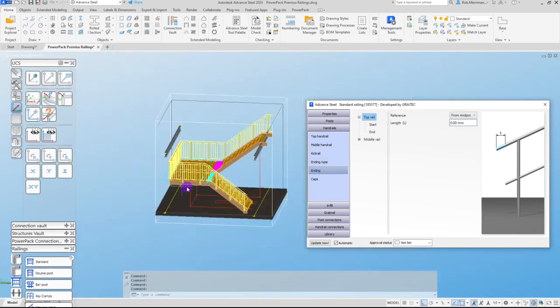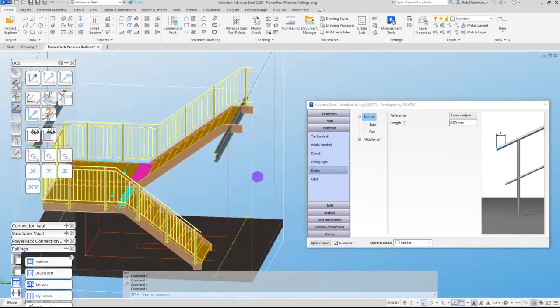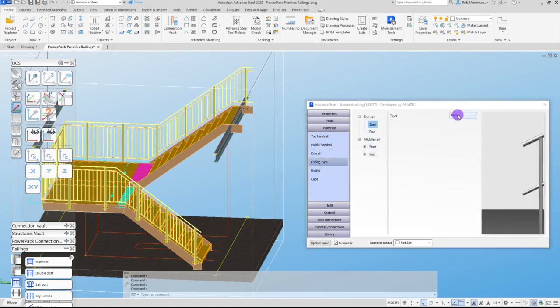The endings in here, at the start and at the end, we've got our ending option, so I can go to the end. Sorry, I need to choose ending type. Then we've got a bent end, we've got an elbow, we've got loop. We've got a couple of new options. Return to wall, so we can return to the side. Or we've got a swan neck, so we can put a swan neck in, and we'll look at swan necks at this position in here shortly.